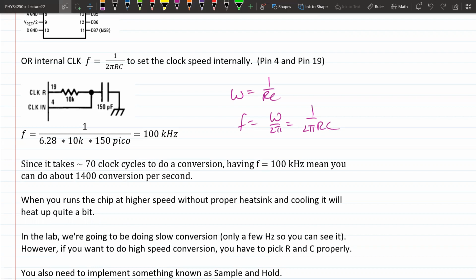What's the size comparator? Well, you can make like 255 op amp comparators onto a chip that's pretty small. But the number of parts in the successive approximation ADC is like 30, right? Where to do the flash ADC, you need like 255 plus 255, 255, and then a crap load of diodes. So like 1,000 parts, right? So there's the cost difference. And however you can shrink those things, that's the size, right? So probably the smallest successive approximation ADC you can make is going to be like 40 times smaller than the flash ADC, just by the number of components.